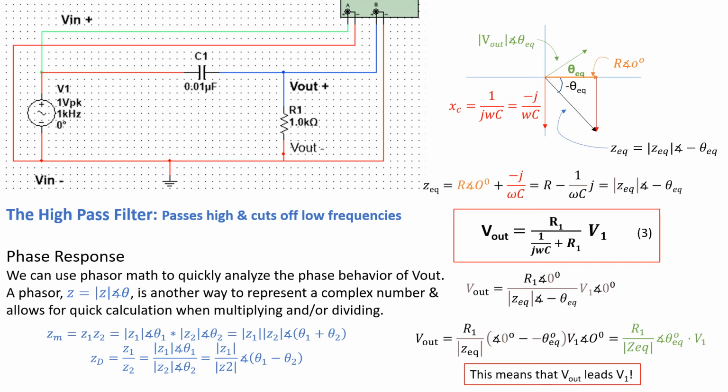The Cartesian form of complex numbers is useful, that is, computationally fast, when adding voltages, for example, when voltages in series are added. When dividing or multiplying voltages, phasors, or the polar form of complex numbers, are most convenient. The phasor is a vector in the complex plane. This vector has both magnitude and phase, and these are exactly the quantities we want to derive.